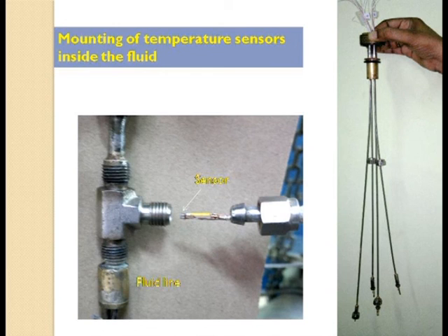Then finally at the outside of this vacuum chamber, you can put them together and seal them by using araldite. Here it is fairly room temperature, so no problem, we can put araldite here, but at these places, all these places you have to do it by brazing. Okay. So this is a specific technique.